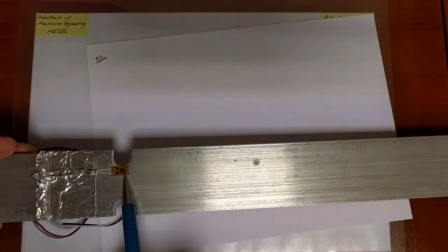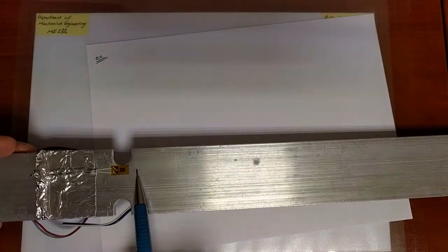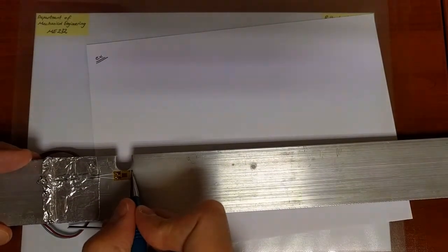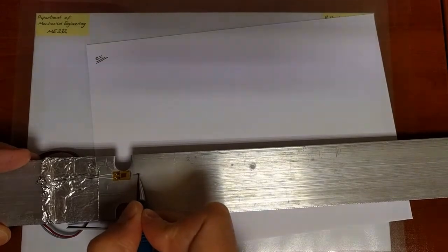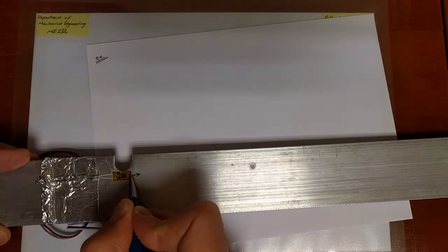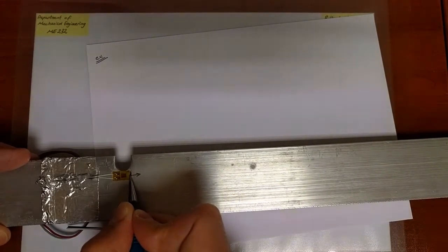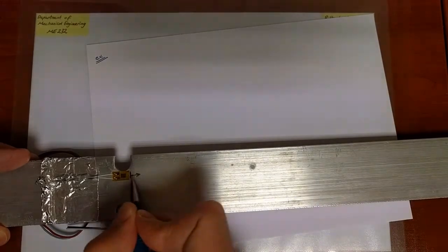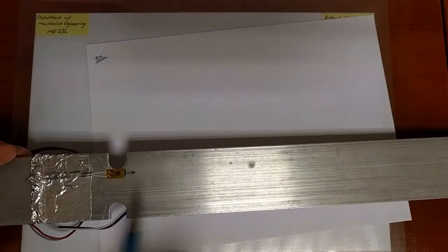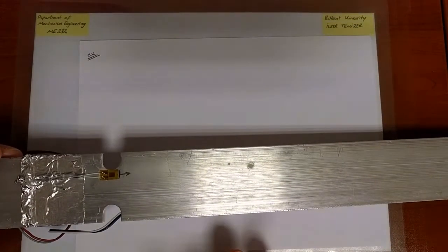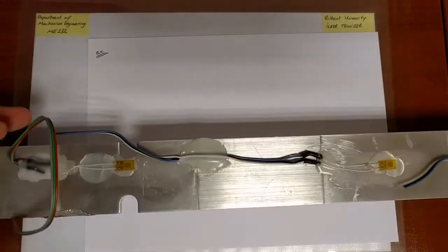So it's measuring a normal strain in a specific direction, or if you like, strain on a plane with normal in this direction. If you orient this strain gauge in some arbitrary direction, then you would be measuring the normal strain on the plane with that orientation. So it allows you to measure a normal strain in any direction that you wish. All right, so that's the concept of a strain gauge.